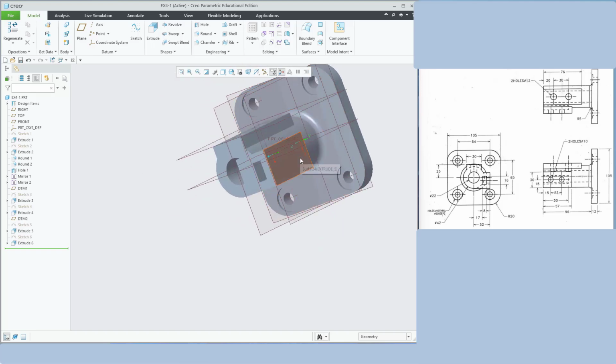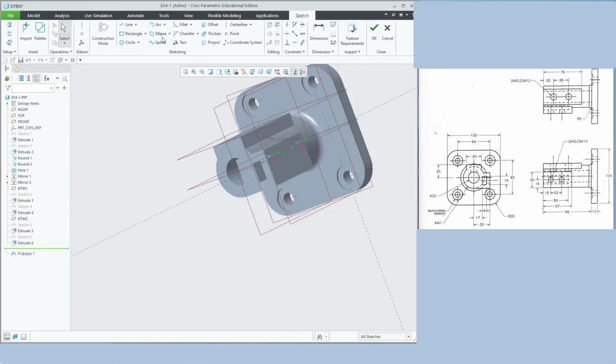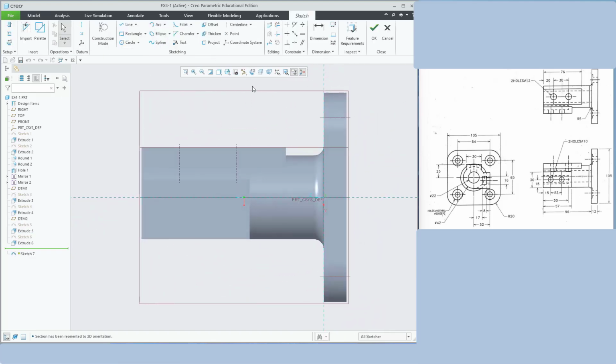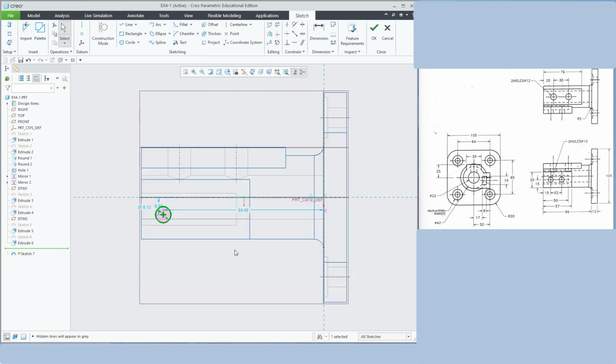So select this one, this top surface, go to sketch, sketch view. So for our convenience, if you want, you can go for wireframe, but actually it is in the center. The two holes are there which will come in the center, not in this axis. Okay, so just create a circle somewhere without coinciding anywhere. Okay, so let me use a wireframe.